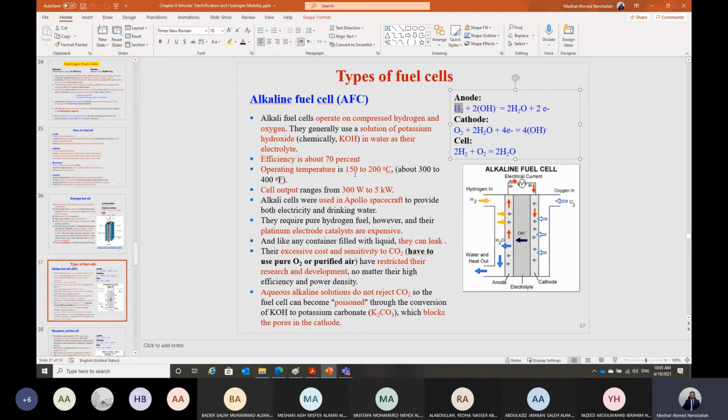Usually fuel cells, hydrogen fuel cells, all of them, work at a slightly elevated temperature to have this reaction activated, and also to use a slightly cheaper catalyst, because at low temperature we have to have a high-priced catalyst in order to activate the reaction to ionize hydrogen and oxygen. This kind of alkaline fuel cell, shabab, has a reasonable electrical power output, and it was the first one. It was used in the Apollo space aircraft.